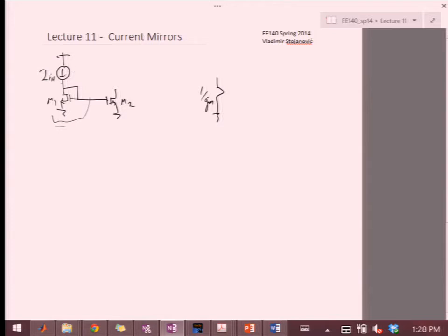We are pretending that this I in also has a small signal component, right? And so here we're going to get some i in. And then on the other side, this will be our VGS1 equals VGS2. And then here we have gm VGS2, and then we have ro2. And this is IO, and we essentially get VO.